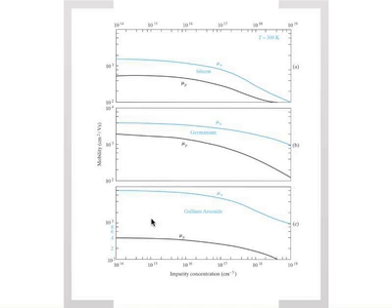No? Okay. Remember, the mobility in a given material depends on the curvature of the band. It depends on the effective mass. We talked about this specifically. For gallium arsenide, the curvature is very large for electrons, which means that the effective mass is very low. Mobility is high. The opposite for holes. You can have huge differences, of course. That's what you see. These differences between the different materials come from the band structure, clearly. Keep that in mind. You should be able to make those sorts of connections. And these are log scale, so these are very big differences, as you can see.